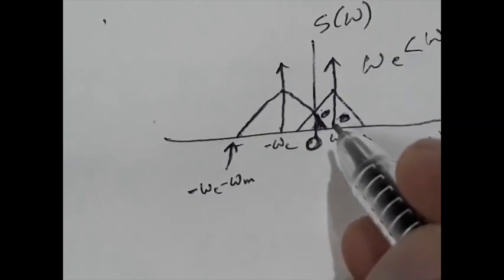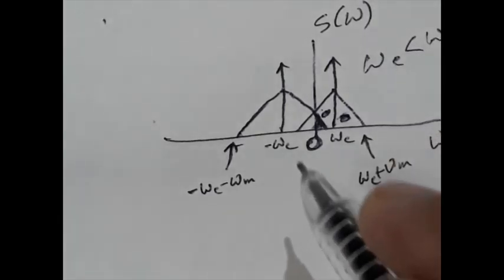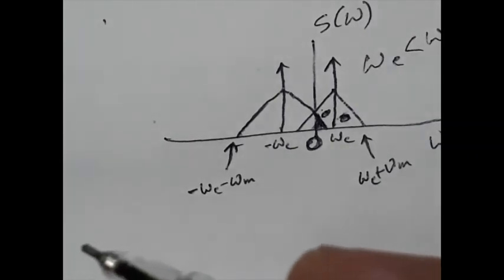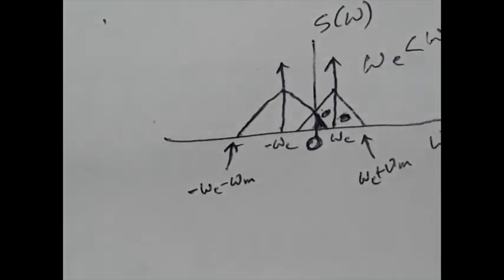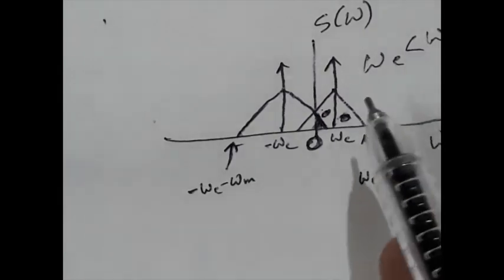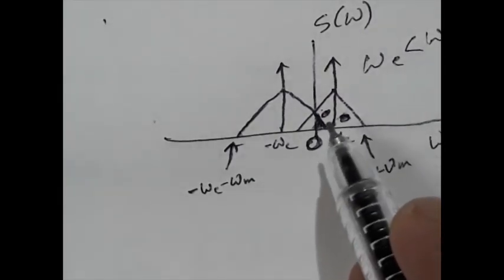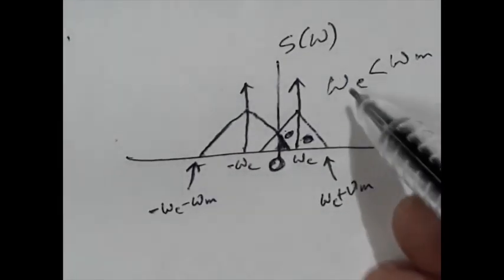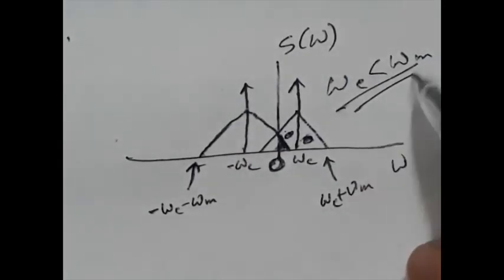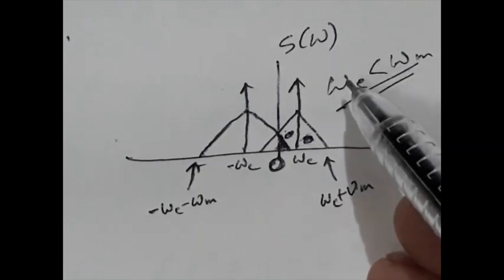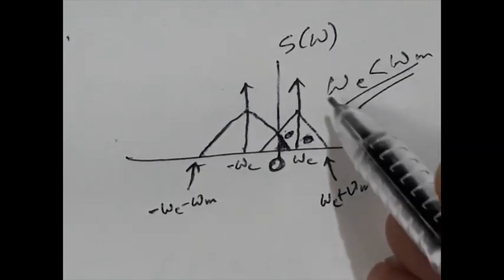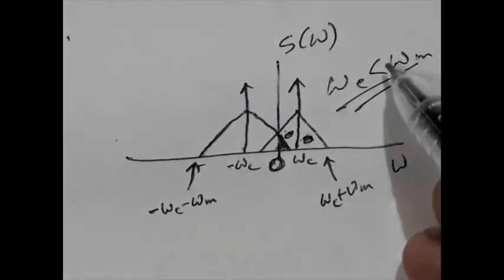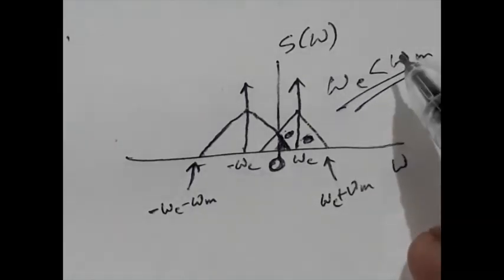That means the main objective of transmission is lost, because you cannot recover the original message signal because of this overlap. That is why this condition is never used in communication systems. So we have to keep the carrier frequency higher than the baseband frequency. Reverse is not true.